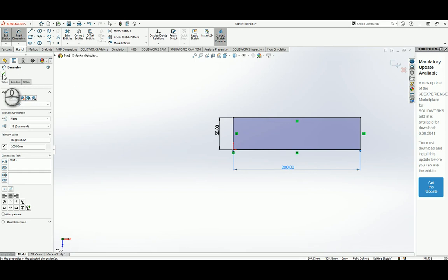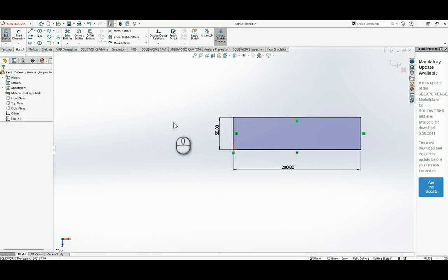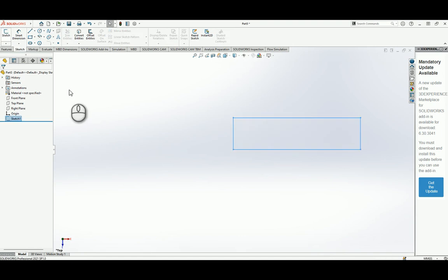So at that point, we could click on the plus sign at the side to get off the dimension, because we were still in the dimension mode here. And then we could click Exit Sketch up here, or we could click it over here. Alright, so we could click Exit Sketch. So we have our sketch. And you could recall just now it was light blue, which means that it is a closed loop, so that we can extrude it.